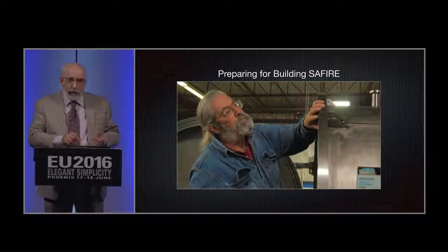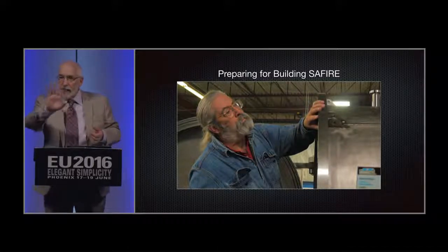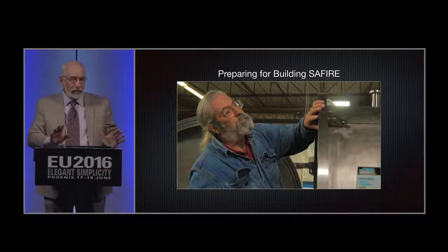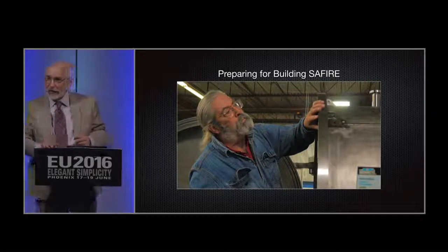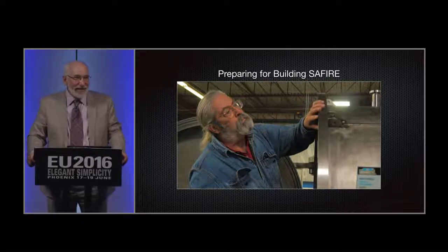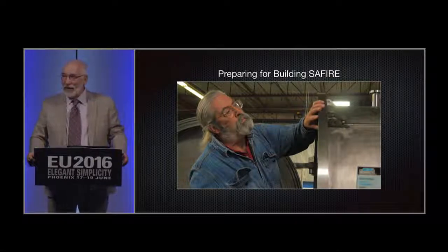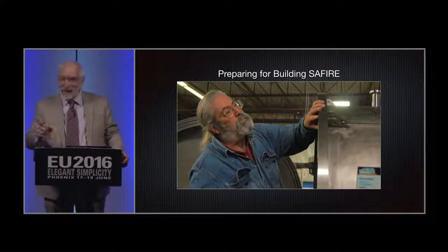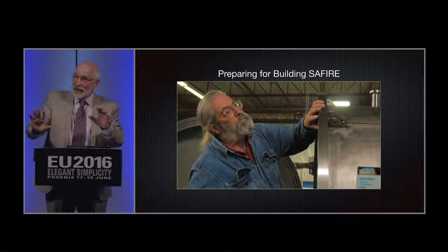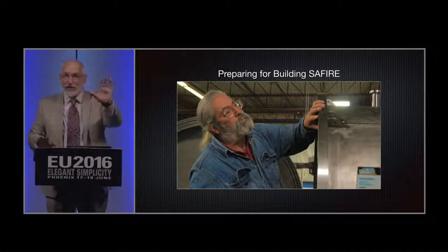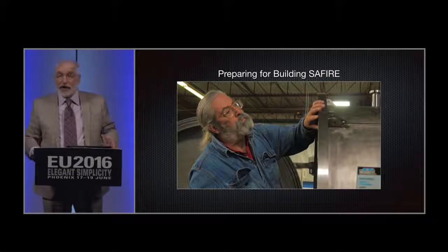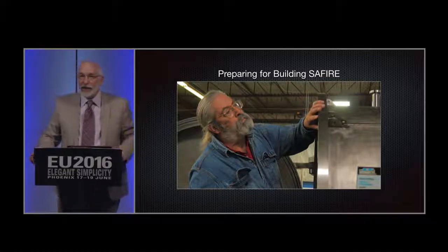And part of the preparations, of course, is, if we've got a scratch on the surface that's got a gasket, it's got to be polished out. This is Scott, and he offered his assistance, free of charge. He asked me, you got a job for me? And I just had the job, and I said, here's a stone. It's a very fine stone. You see this big lip across the chamber here? If you see any imperfections, see if you can pull those out, because every imperfection means that's where we're going to have a gas leak. Just to let you know, Scott, we don't have any leaks in the chamber door.